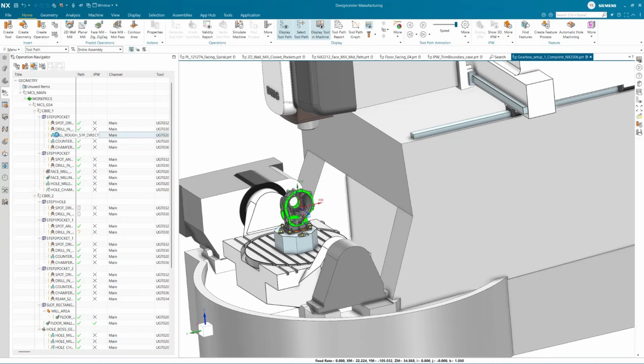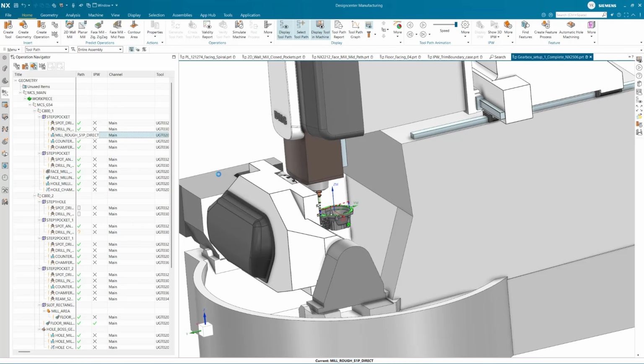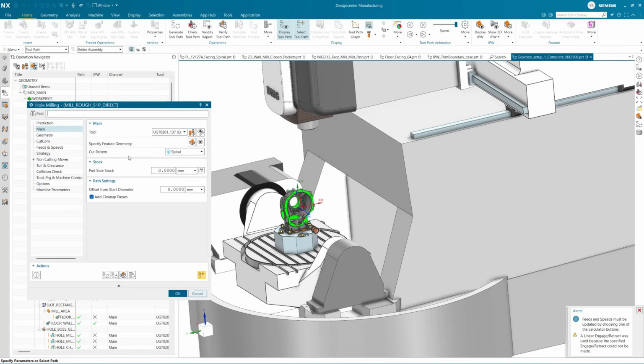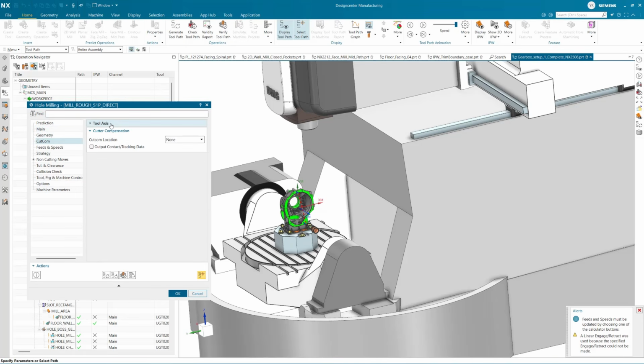If I go to my toolpath, I can easily select the required tool axis rotary axis solution. It's located under the tool axis option over here. Right now, the solution is selected as A90 and C-90, whereas we can change the rotary solution from that location to A-90 and C90.